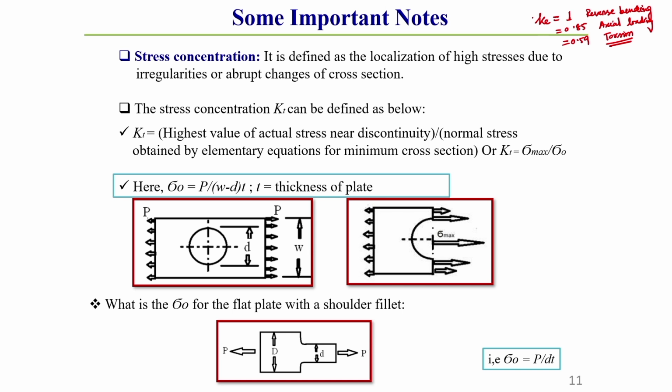Now, another factor is the Kg factor, called the miscellaneous modifying factor. One of the very important miscellaneous effects, related to welding, is generally based on the stress concentration factor. We will show how this Kg value varies if the stress concentration effect is considered.